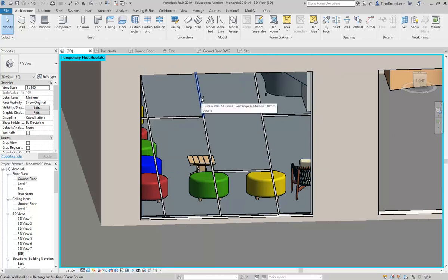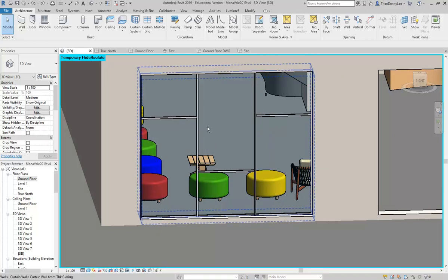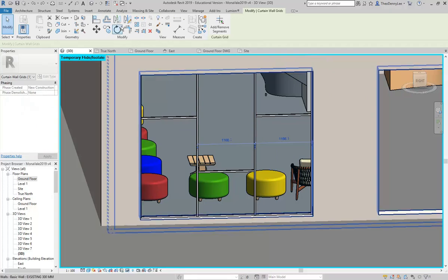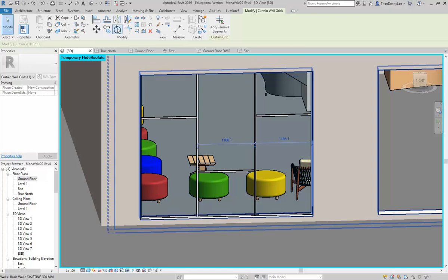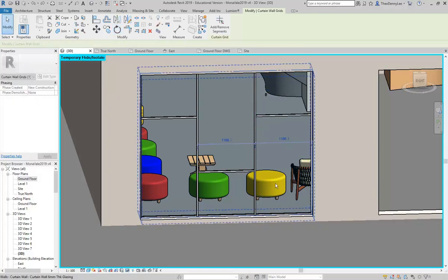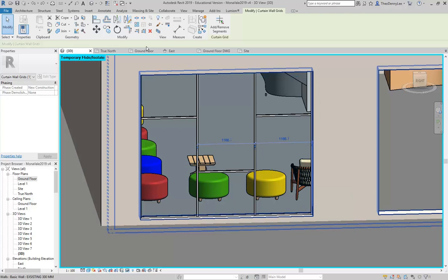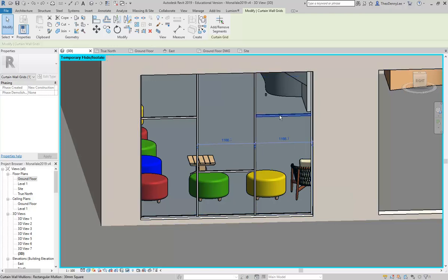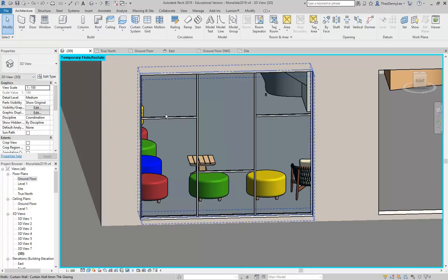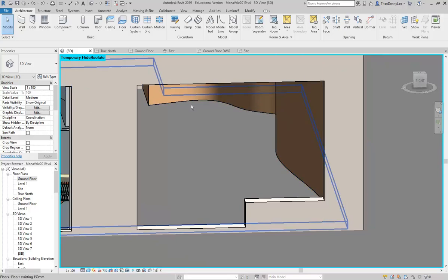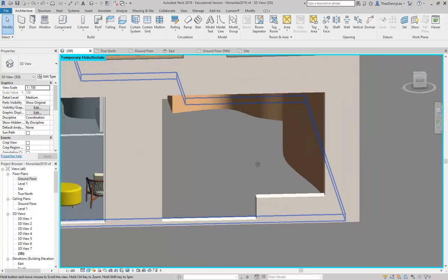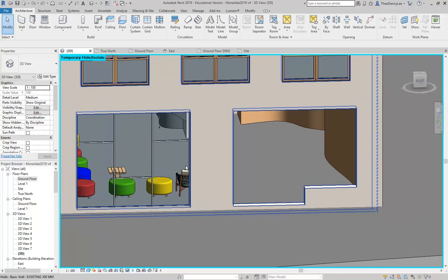So if you want a series of different angles, let's say I want this grid line to be a different angle to this one, you'll see when you select grid lines, if you try to rotate them individually, nothing happens. And so that's the limitation with grids and these automatic curtain walls. Now, it doesn't mean you can't do more complex patterns, it's just that you would do them slightly differently. But maybe I'll show you that because it's a good thing to think about.